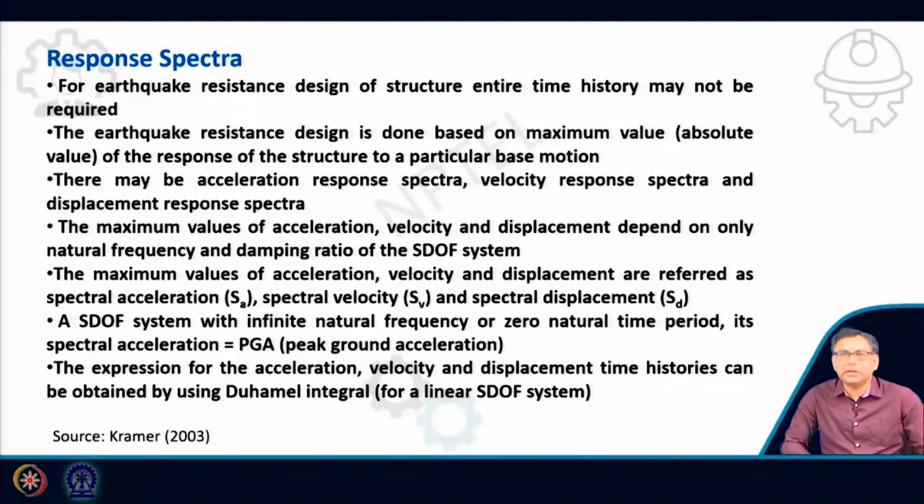Harmonic loading, then periodic loading. In periodic loading, we have to convert the load to a series of harmonic loadings. That means we will convert it to a Fourier series, then we will get the response, and then we will get back to the response of the input motion. Now, there may be acceleration response spectra, velocity response spectra and displacement response spectra.